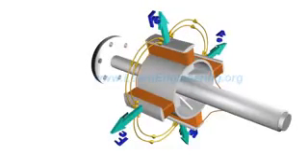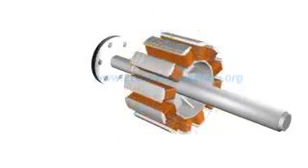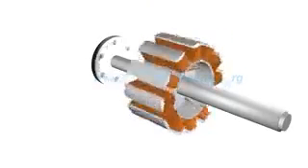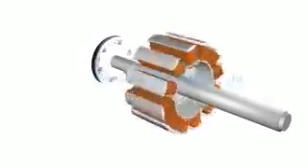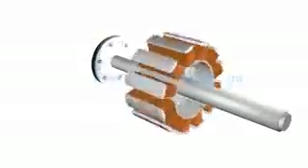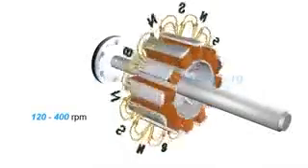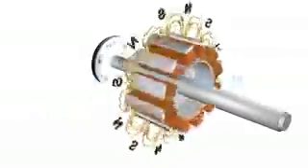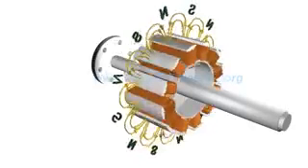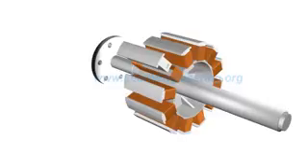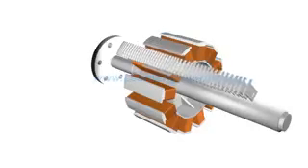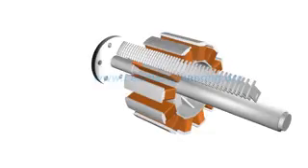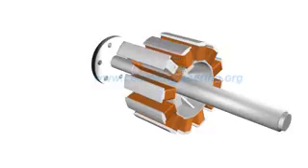So salient pole rotors generally have 10 to 20 poles, which demands lower RPM. Or, salient pole rotors are used when the prime mover rotates at relatively lower RPM. The pole core is used to effectively transfer magnetic flux, and it is made with fairly thick steel lamina. Such insulated lamina reduces energy loss due to eddy current formation.